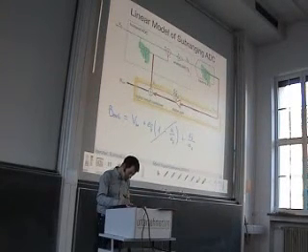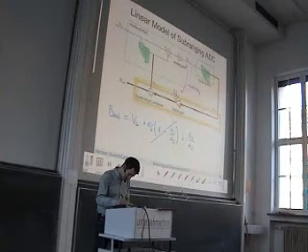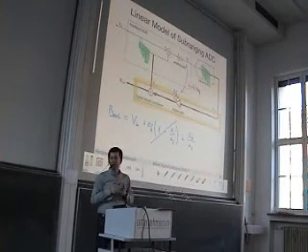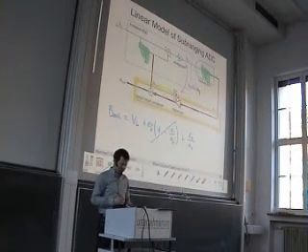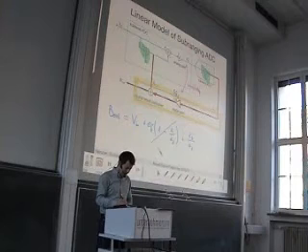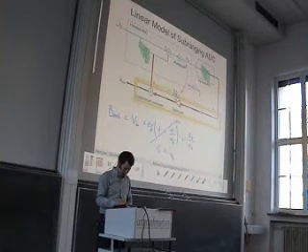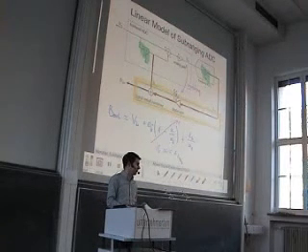So we need a good matching between these two A's, which does not mean a matching in a layout sense, of course, but which means that the A and the AD have to be equal. So this one cancels out, this goes to 0 if A equals AD. This is the requirement that we have here.